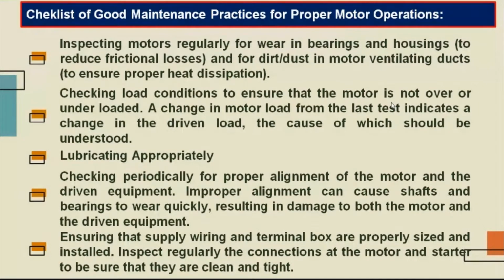Next is checking periodically for proper alignment of motors and the driven equipment. If there is improper alignment, it can cause the bearings to wear quickly, which may result in damage to both the motor and the driven equipment. If we take the case of a paper mill or textile mills, there are a large number of driven equipment which are driven by motors. So there should be a proper check of the alignment, whether the alignment between the motor and the driven equipment is proper or not.